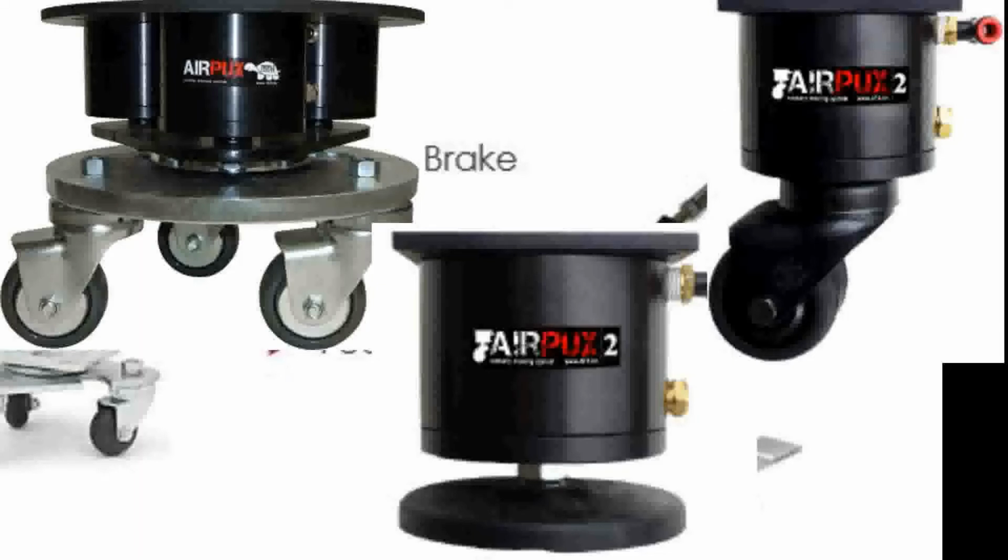That pressure has been dialed in to lift the weight of the wagon that you're trying to roll and push the casters out onto the floor. Then you can roll the object freely while the air power is engaged. And then when you cut the air power, the bladders slowly let their air out. The casters are receded into the base of the platform, and the platform sits on the ground.